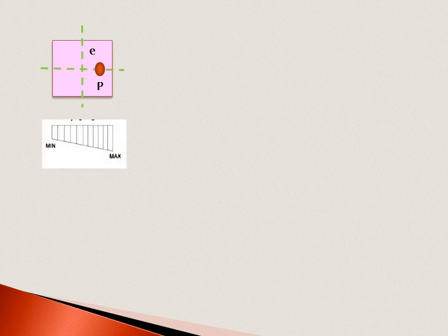Now see the different examples of maximum and minimum stresses. Consider this is a section having B and D. This is the axis of the member and load P is acting on the right side of the axis YY at an eccentricity of E. Now see the position of maximum bending stress and minimum bending stress. The load is acting on the right side of the y-axis, therefore maximum stress is on the right side and minimum stress is on the left side.